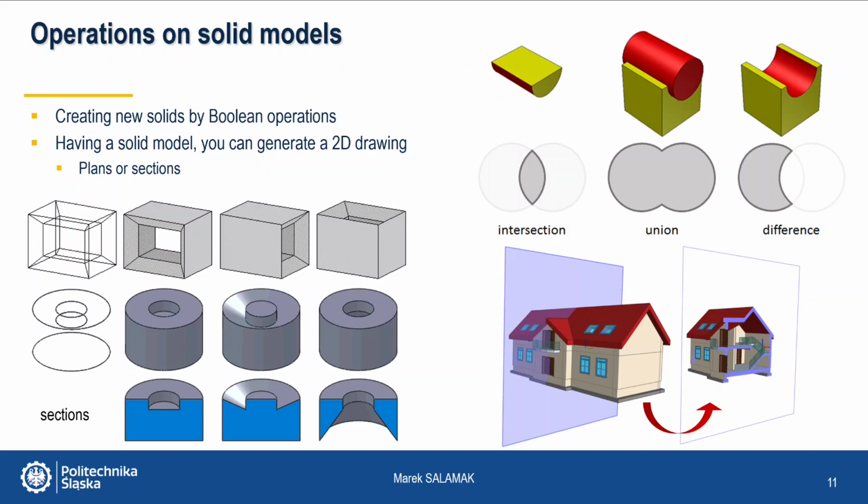In this way, it is possible to create more complex solids from primitives. Interestingly, these solids remember the history, making them easy to edit. Having a solid model, you can almost automatically generate a 2D drawing in projections or sections of the solid model.